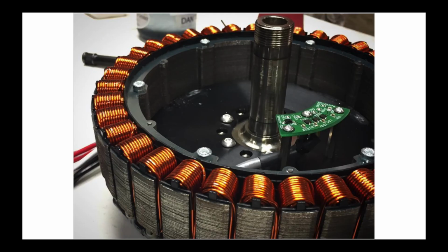Here's a picture of a Mitsuba M2096-3, one of the more common solar car motors, clocking in at around 95% efficiency. This motor sticks to the traditional Hall effect sensor, using a very clean PCB standoff system for mounting. Here we can see the ultra-thin nickel lamination stacked very tightly, all bolted together with an evenly distributed bolt pattern.